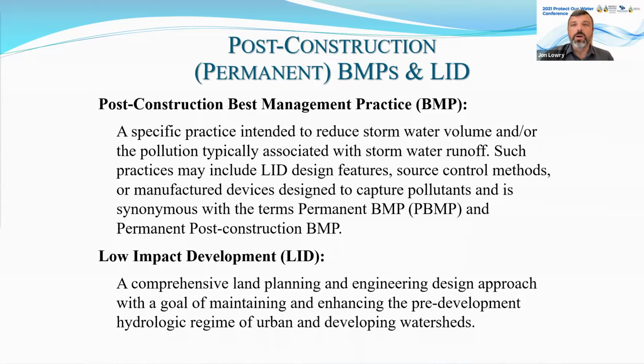They provide long-term stormwater treatment. The focus we're trying to get implemented the most are low impact development BMPs, like bioswales, grass swales, anything that tries to maintain the pre-existing site conditions. We'll get into a little more detail about that as we move on.